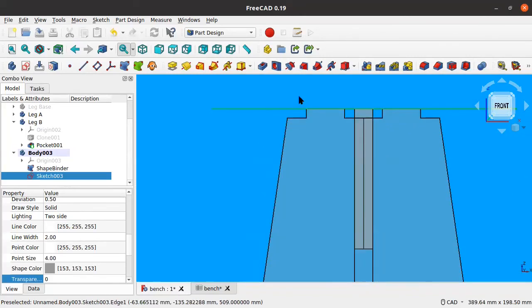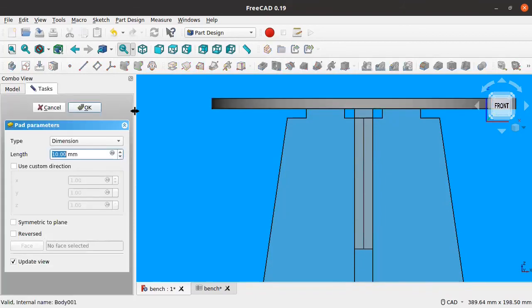And we want the surface to extrude both ways, so the seat touches the supporting element, the leg structure, and it also goes a little bit upwards, thus hiding the actual finger joints. So we can use the pad, selected sketch.